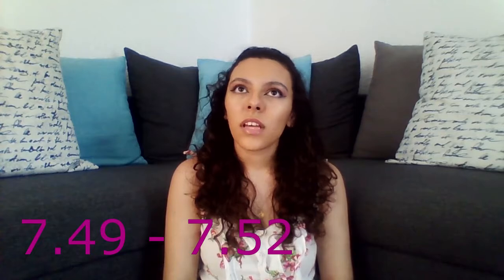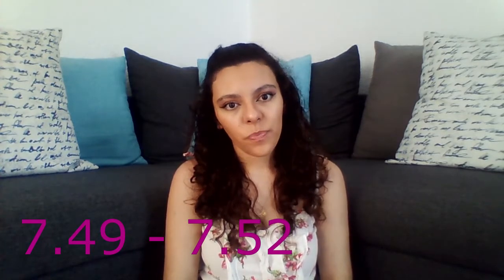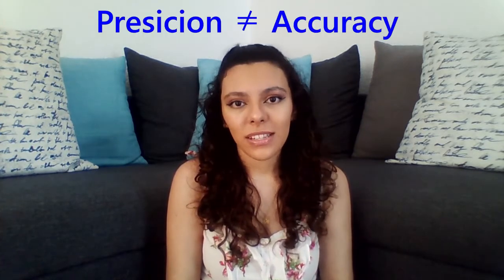Precision refers to the closeness of 2 or more measurements to each other. An example might be a pressure gauge with a measuring range of 0 to 10 bar. If it measures 7.49, 7.5, 7.51, and 7.52 alone over a certain time in the same conditions, it means that the instrument has great precision because the maximum difference between the measured values, that is 7.52 minus 7.49, would be of 0.03. It should be noted that the precision and the accuracy are not the same, and that precision is synonymous with repeatability, which I will explain later.